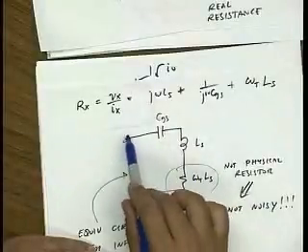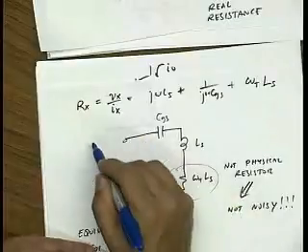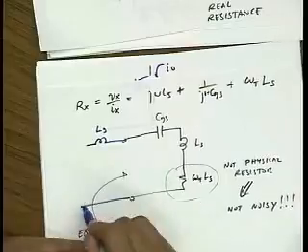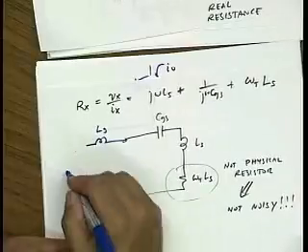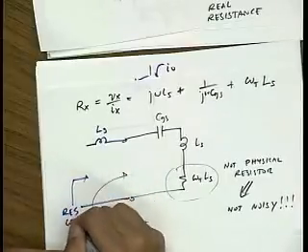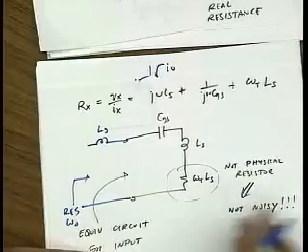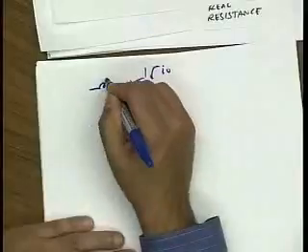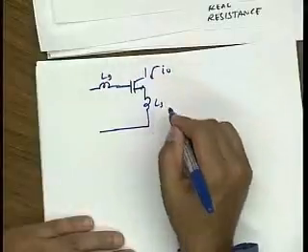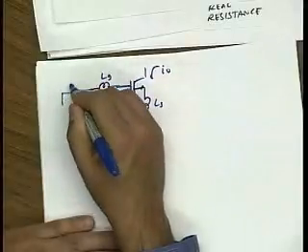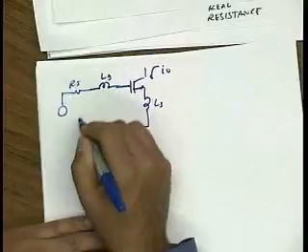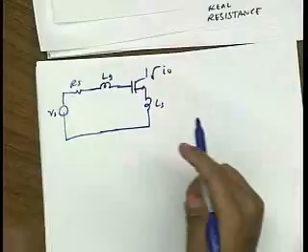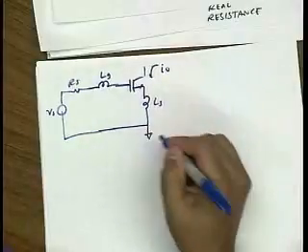So I could just add some inductance in series here, call this LG, and move the resonance frequency, making this resonate at omega naught. Okay, so let me calculate the current gain under those conditions. So this is LG, this is LS, and then I hook up RS here, and this is VS. And I want to find the current gain of this circuit.